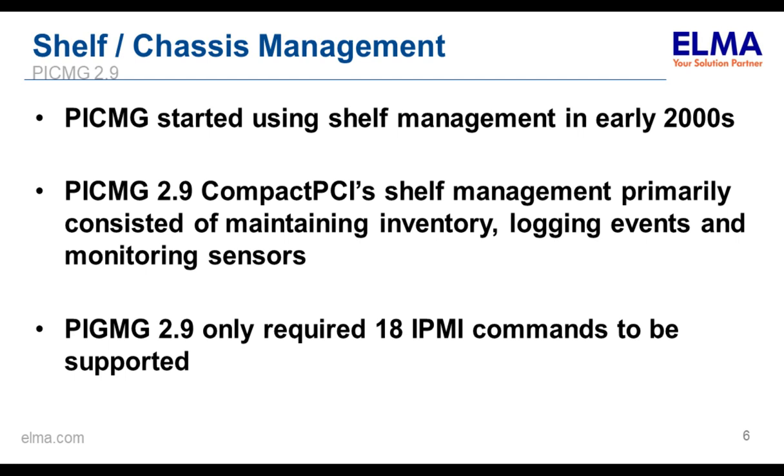And that started with PICMG 2.9, which is the compact PCI chassis management, which primarily focuses on maintaining inventory, logging events, as well as monitoring some sensors. PICMG 2.9 only has 18 IPMI commands that it requires, though there are several optional IPMI commands that you could support.